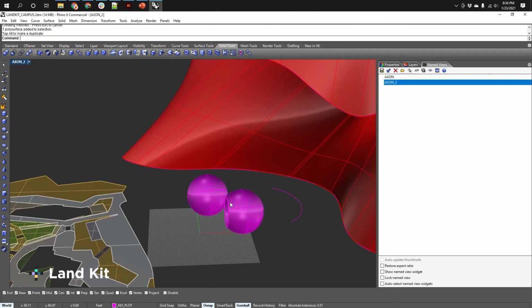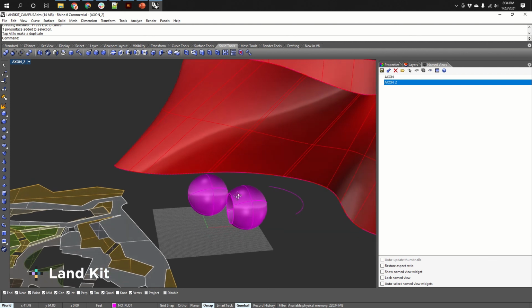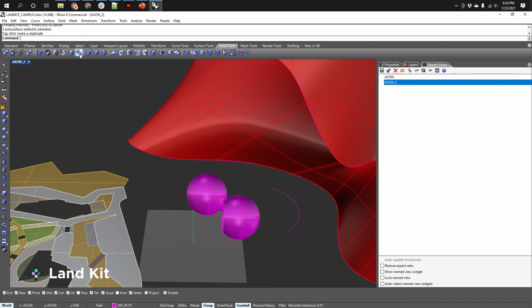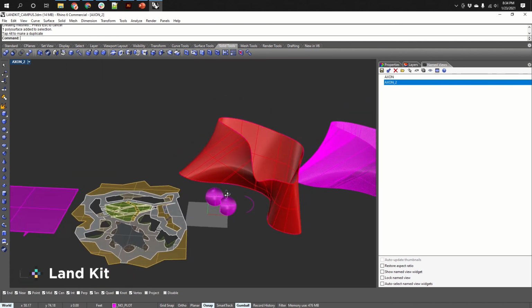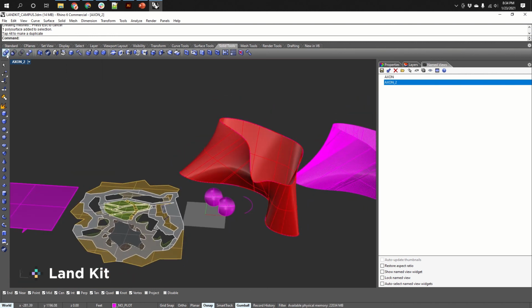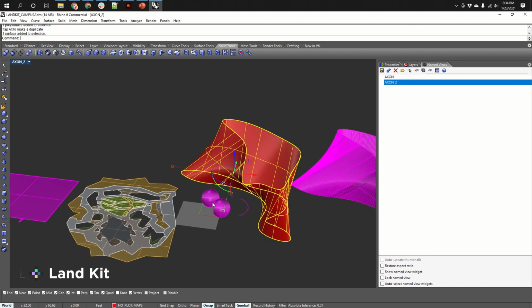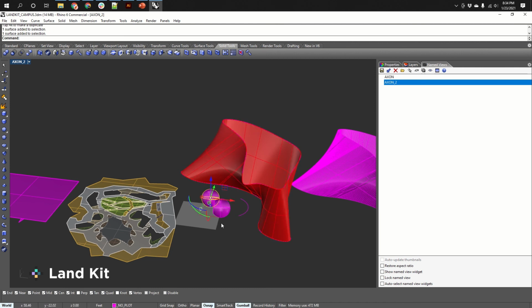And you can do different kinds of Boolean operations. You can do a Boolean union, which joins everything together. You can do a Boolean split, which splits it into all the parts of all the different overlapping pieces, I believe. There's intersect, which will do only the space between the two. You can do difference, which we just saw. There's a lot of different options there. You can do filleting, but the point here is that these are all the Boolean operations. The point is that surfaces and solids are both made of the same thing, but a solid is a solid if it's closed.